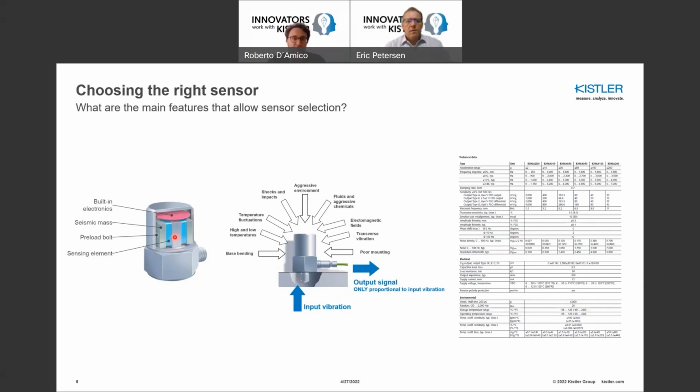This electric charge will be measured, but here the whole point is that we are moving from a mechanical input to an electrical quantity. Your goal, and also our goal as a sensor manufacturer, is to make sure we control the relationship between the input mechanical vibration and the electrical output. There are design elements that make sure this relationship is consistent, but there are also some parameters which react to external influences, because in most cases these sensors are put into aggressive conditions.